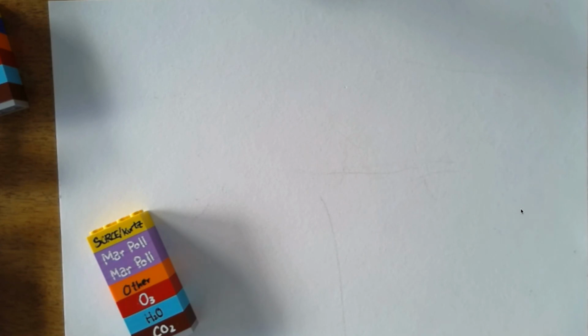First, for Santiago, if we determine the typical climatological spectrum that we expect, we can start to engineer the semiconductor, the thickness, and the doping, to optimize for that specific climate. The other way to look at it is that if I have a particular design of solar cell, where should I target it? Where should I deploy it? And that depends on the aerosol climatology and so on.